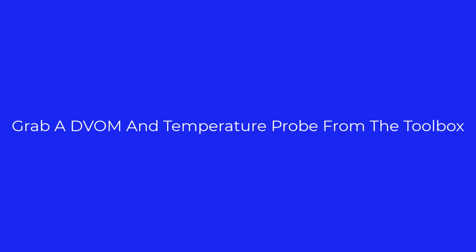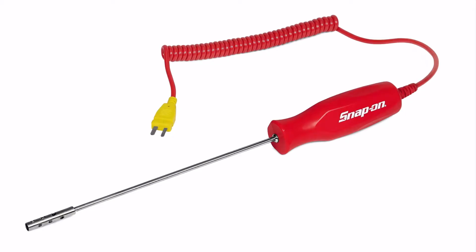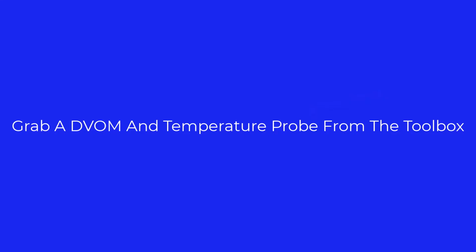For this next section, you're going to need to grab a DVOM and a temperature probe from the toolbox. So you know what the DVOM looks like by now, but this is what the temperature probe looks like. You're going to snag that out of the toolbox along with the adapter that comes with it, because you're going to need this to check the temperature going into and out of the heater core.